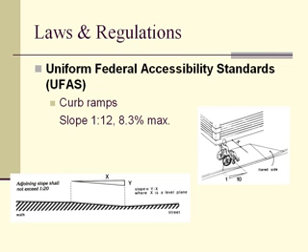So if you think of a curb ramp for a parking space, the slope at the gutter should be no more than 5%, because otherwise the transition from that 5% to a 12% creates an area where a caster on a wheelchair can get trapped, and somebody can tip and move forward and fall out of their wheelchair.